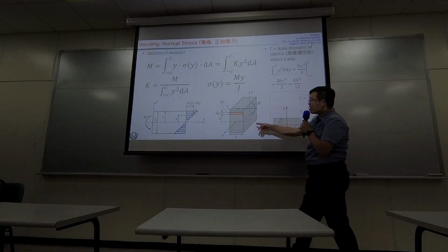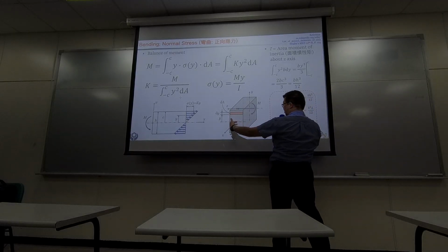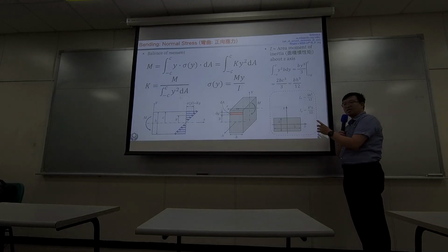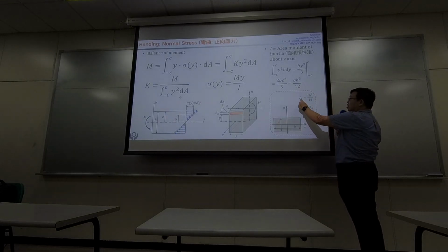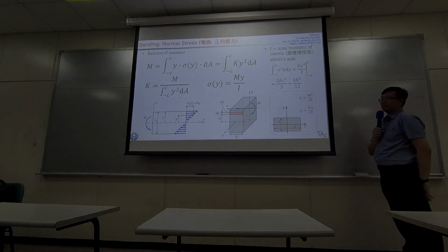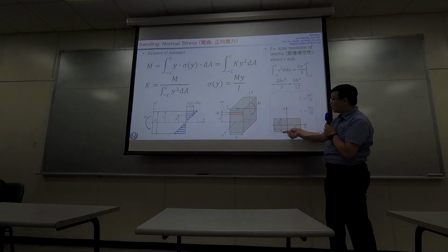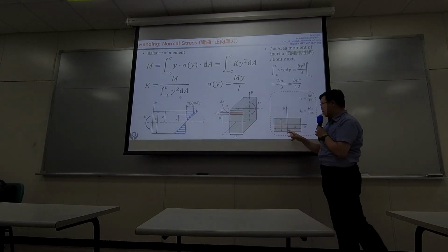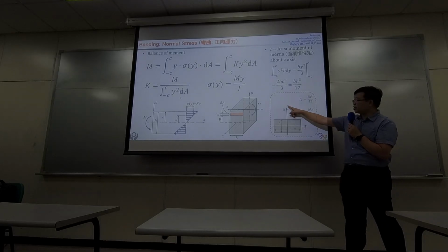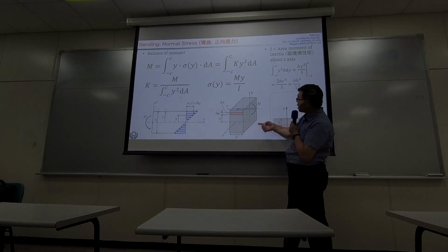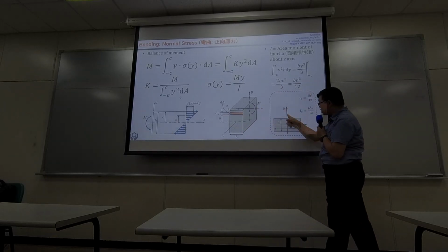Okay, so for the square cross section, like this. Now, if you have your coordinate system, usually from the textbook, you can check the back side, the last several pages of the textbook. You sometimes see this, or you can Google for it. Sometimes it tells you Ix and Iy, and you draw a picture like this. In this particular case, this is B, same as our B right here. This is H, same as our H right here. Same math symbol, but the coordinate is different. Over here, horizontal is X, vertical is Y, but in our figure, horizontal is actually Z, and the vertical one is Y.